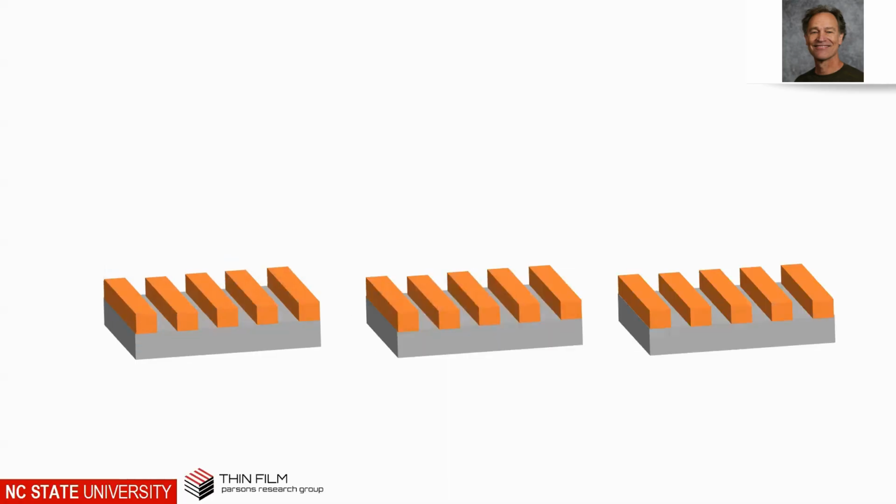I'm going to show you this a little bit differently. So this is the light. I didn't put in here the photoresist, but this is the light shining down, and this is where I want to put my film, and it's perfectly aligned. See those yellow? That's the light coming down. The light is perfectly on register with the metal, with a line underneath. And if I do that, then boom, I can deposit that metal exactly where I want it.